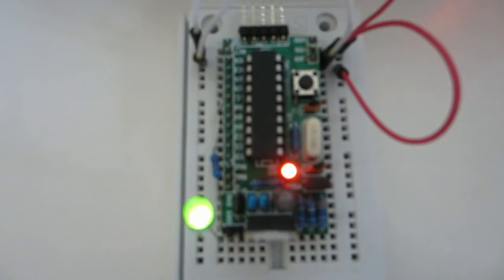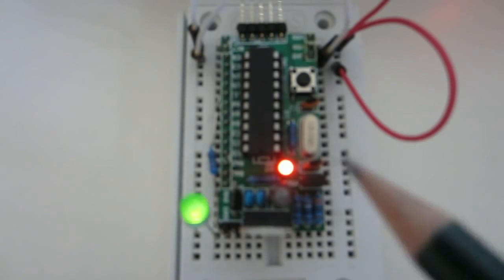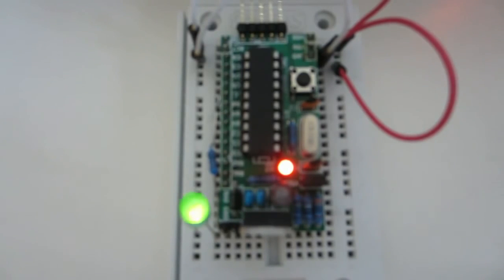And by varying the duty cycle, varying the time the LED is switched on, we can actually vary how bright it is. It's called persistence of vision, and it's basically because our eye cannot determine the fast on and off switching, because it's so fast that it looks like it's constantly on and it's just fading from 0 to full brightness.